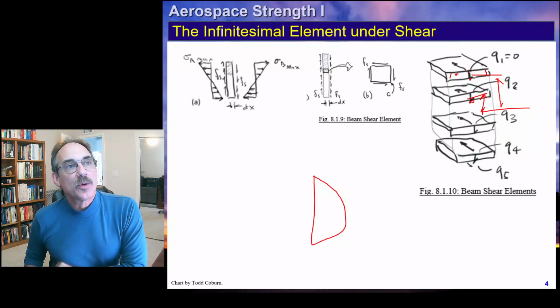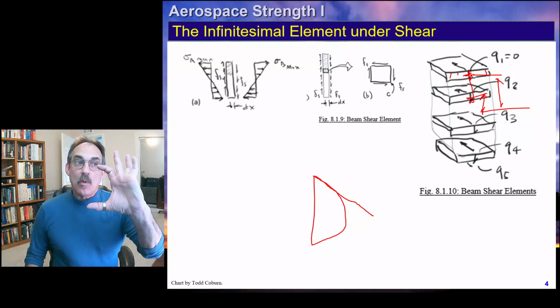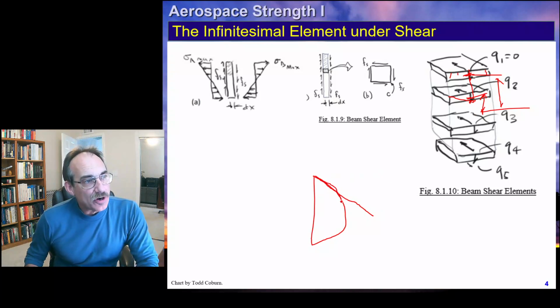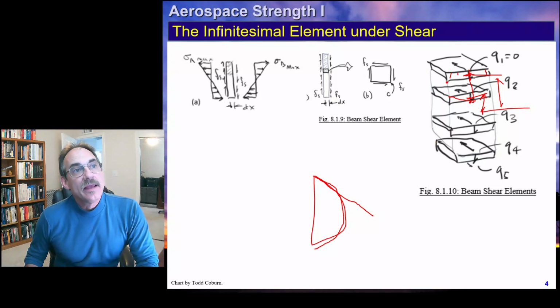If we only were increasing the area from like 1 inch of area to another inch of area to another inch of area, we would see an increase in shear stress like this. But you'll notice this first little slice is out here with a bigger Y than this second slice, which is smaller, which means we're taking this area and multiplying by a big Y, and this area and multiplying by a smaller Y, and this area, and so on, which means we're getting diminishing returns, and that's why this is parabolic.